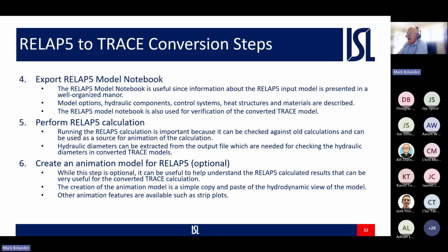And then it's always a good idea to perform your RELAP5 calculation before you convert. That way you've got a basis for comparison of RELAP5 to your TRACE calculation to make sure that everything is running the way you expect it to.